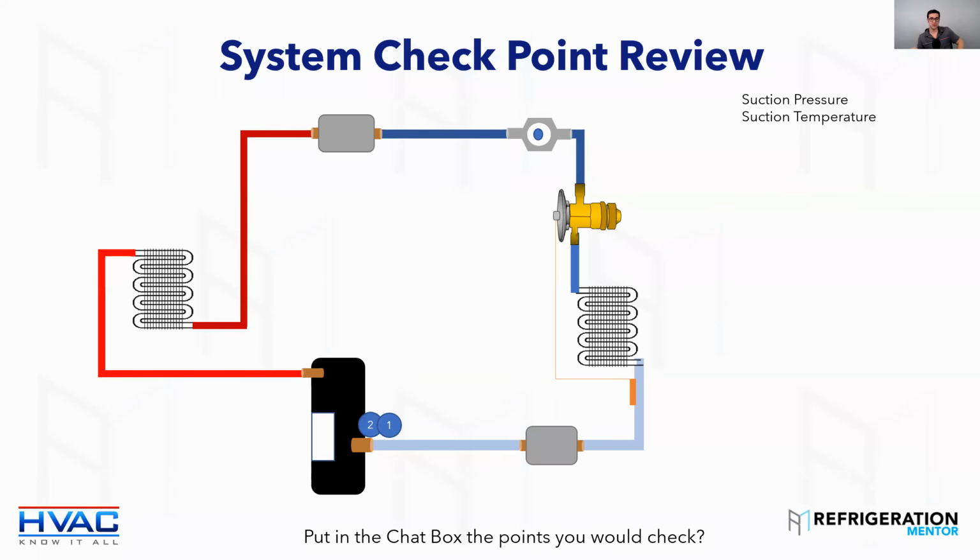Sometimes I've seen it many times where the manufacturer who builds the equipment says a certain refrigerant's approved, but then when you go to the compressor manufacturer, it's not approved for the compressor. Doesn't mean it's not going to work, but it doesn't mean it's going to work very long either. Suction pressure, high side pressure, subcooling, superheat, outdoor ambient. Yeah, that's a good one. Indoor temp, amperages, delta T's.